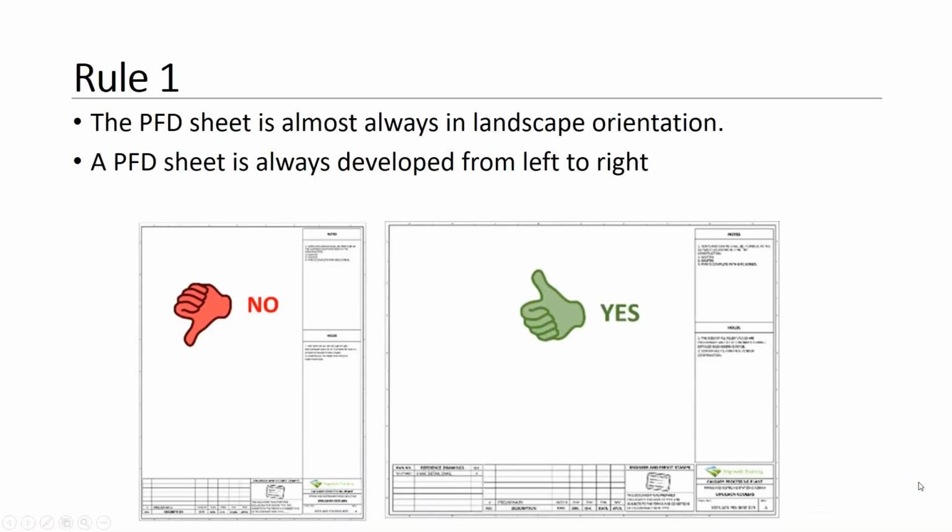Rule number 1. Your PFD sheet should be in landscape orientation. You should develop it from left to right, top to bottom. So avoid any portrait orientation when you are developing your PFD sheet.